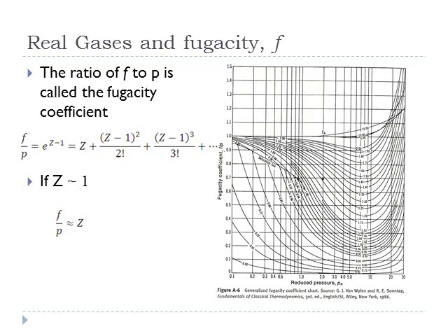And the other case would be you can go up. It's rare, but there are some cases where you can have z greater than 1. That does happen sometimes with compressed hydrogen, in which you're at a very, very high value of P sub r, reduced pressure, and you're at a fairly high temperature, critical temperature. And you can actually get values, but once again, they're not very large. Maybe you go to z equal to 1.1 or 1.05. It's not going to have a very large effect on the definition of entropy change between state 2 and state 1.